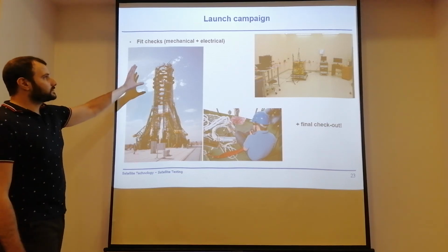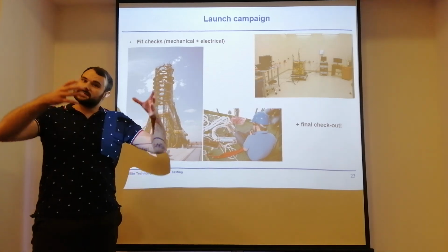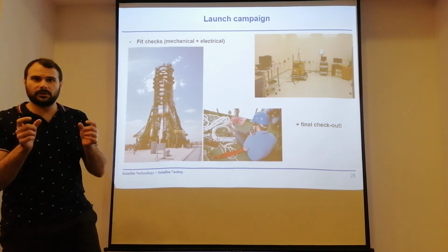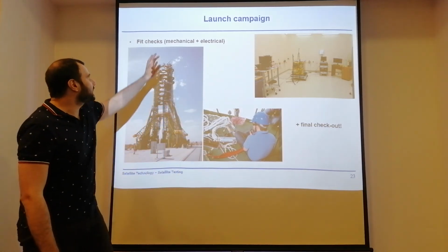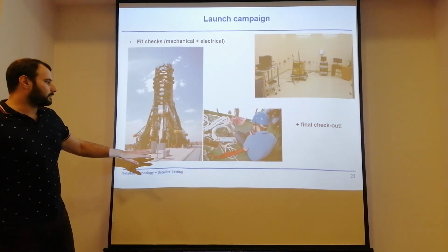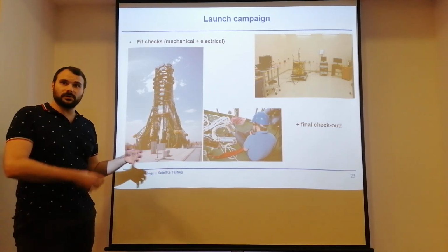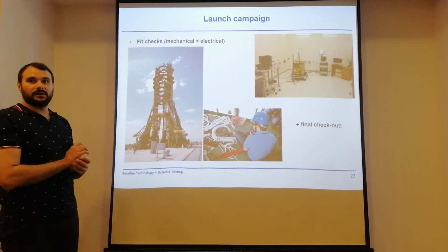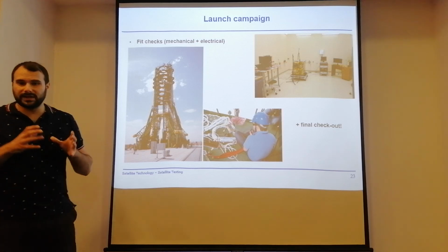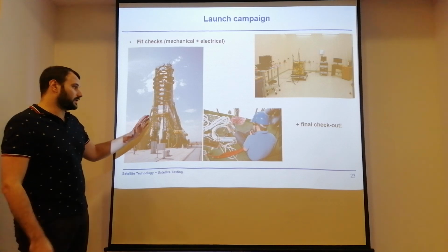Lastly, there were some fit checks to be done, mechanical and electrical fit checks. So there were some tests performed if the satellite would actually fit into the launcher bay for a rideshare mission. So the clearances are all there to the other satellites. This is the mechanical fit check, but also the electrical fit check. You can see here. In our case, we had to charge the satellite even once it was already installed inside of the Soyuz rocket. So in the morning of the day of launch, we connected lastly our battery chargers to our satellite to charge the batteries before putting it into space.